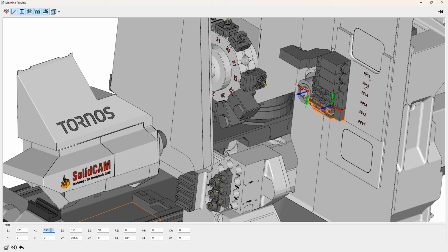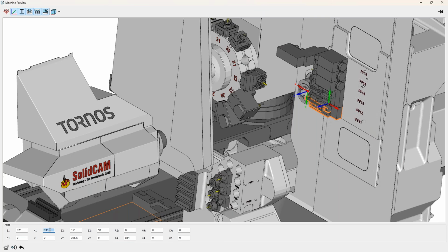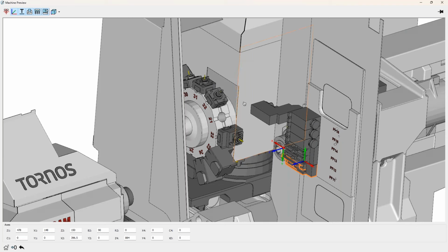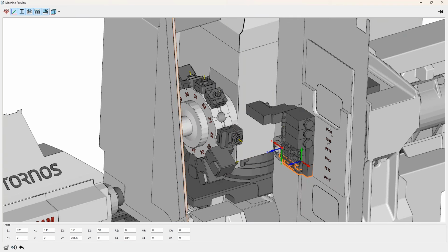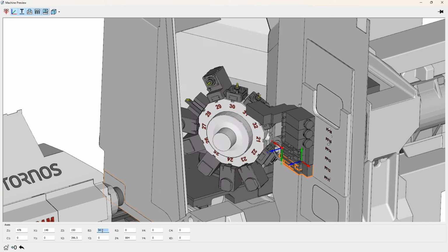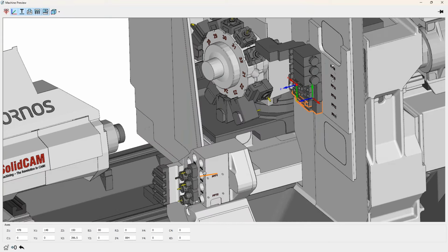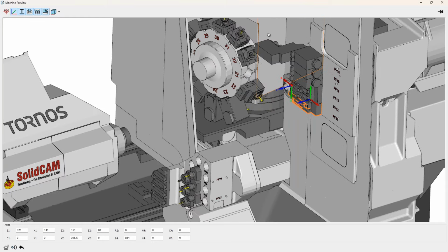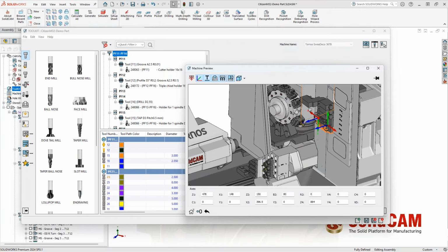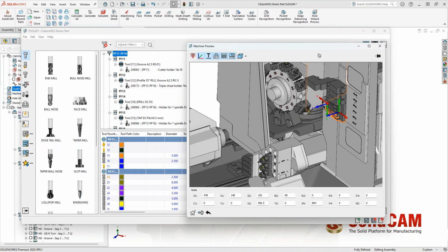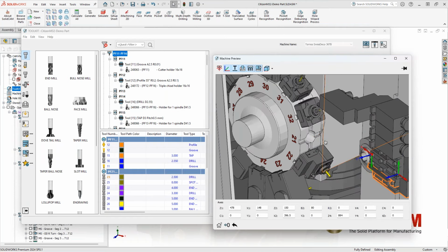Let me just show you a couple of movements here so you can also feel the machine a little bit. It has also another turret, which is a revolver. And what is very unique on this, I would say also among all Swiss type machine manufacturers, is that it has the B-axis on the revolver. Not very often you can see it on Swiss type machines. And this is a 2nd channel, and also on the 3rd channel, there is the sub-spindle with a linear gang also over here.